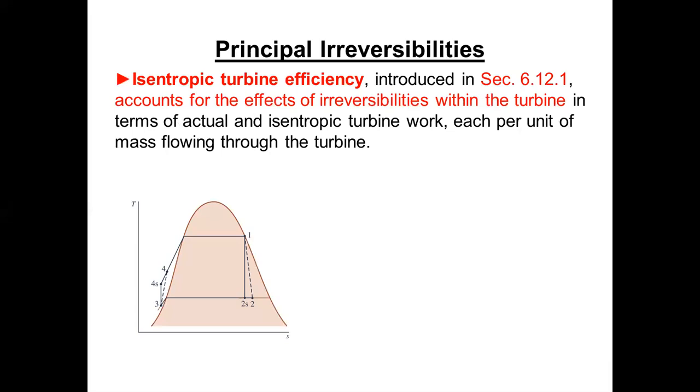The thing is floating on a very thin film of oil, and that oil circulates through the bearing. It comes in on one side, goes out on the other side, so it goes 180 degrees around, and then it goes off to a cooler, and cooled oil comes in at that point and circulates around the additional 180 degrees. And so no metal-to-metal contact.